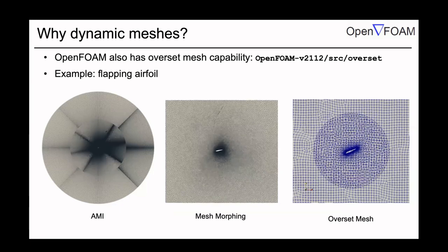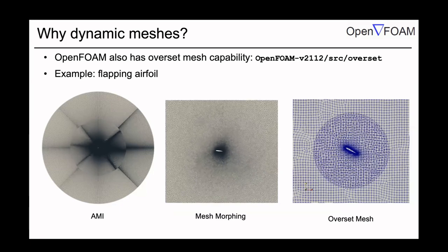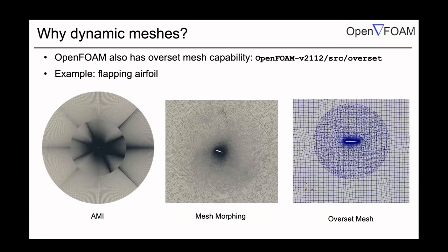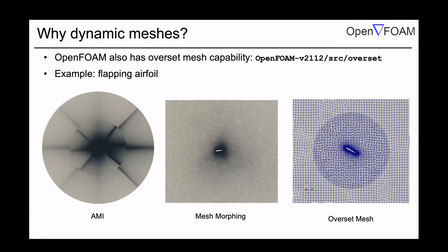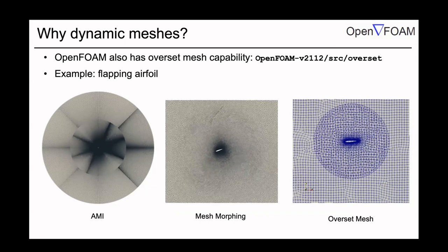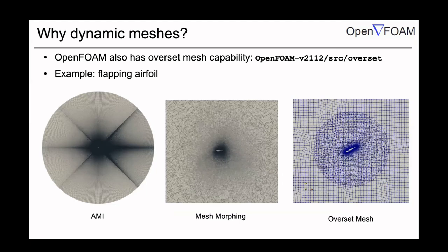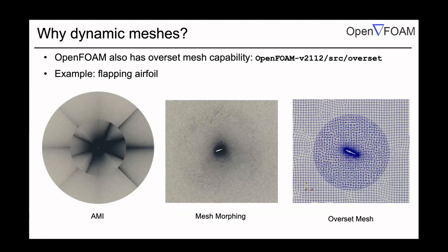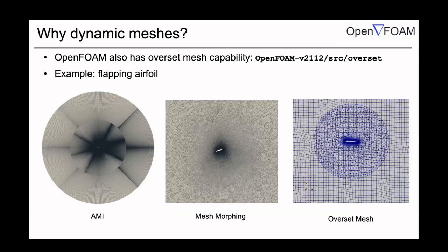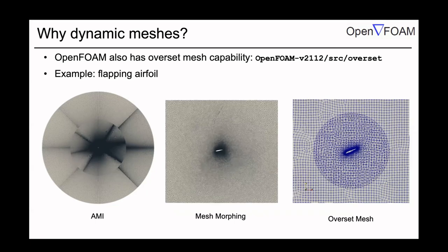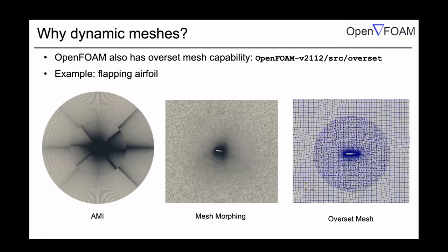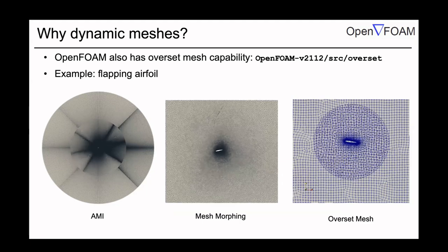However, it allows us to do much more challenging simulations which is not possible through the others at all, because due to the negative cell volume errors, our solution will diverge. However, even if the solution is inaccurate, our solution will never diverge. Okay. So we have to be carefully choosing the interpolation criteria to get more accurate results. But this technique is called overset method.